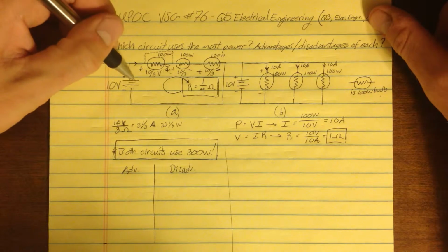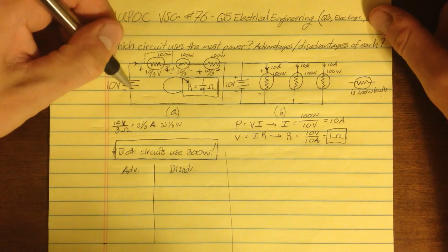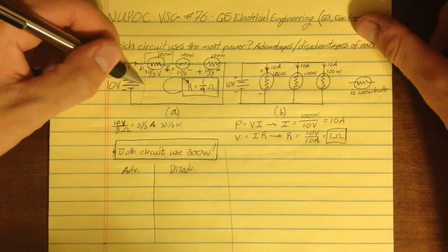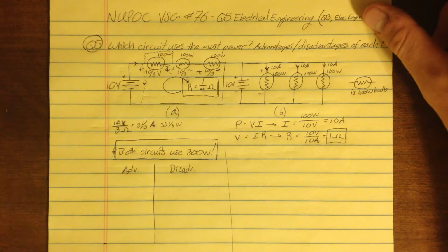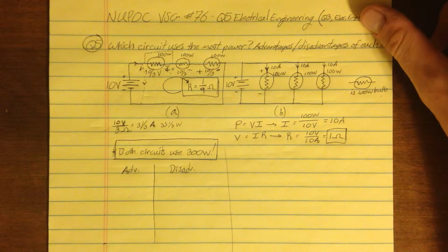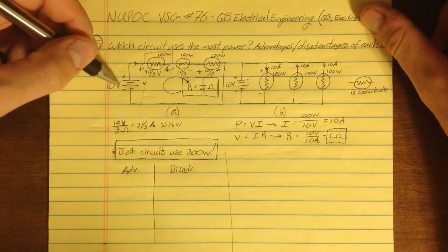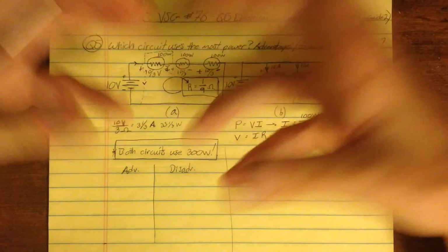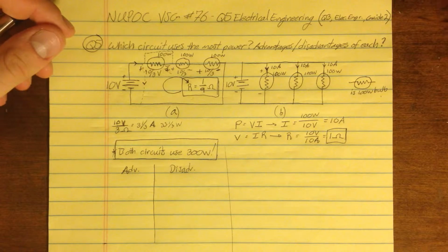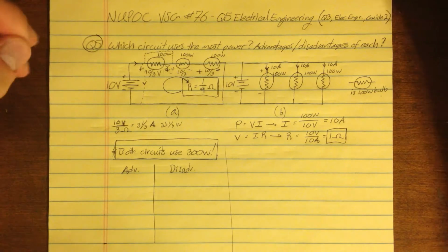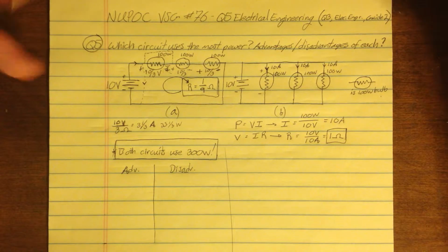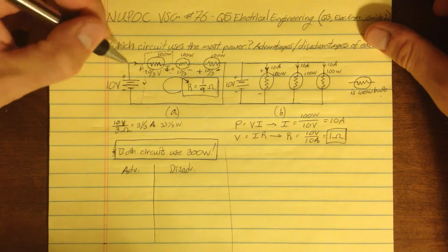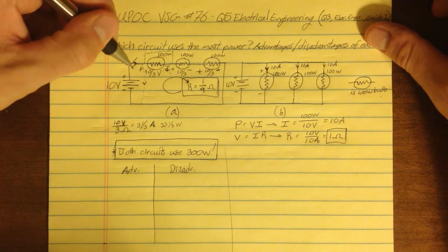short the entire source. And of course, if we short the entire source, for example, if I put a wire from here to here, and there's very little resistance in that wire, then a large current will flow, it will generate a lot of heat, and it'll probably blow out the source. The source will just destroy itself because it'll try to source so much current, it'll heat up, and if it's a battery, it may split open. So that's what a short circuit is. And in a typical power system, we would have circuit breakers that would try to create an open circuit, so break the circuit. That's why they call it a circuit breaker.